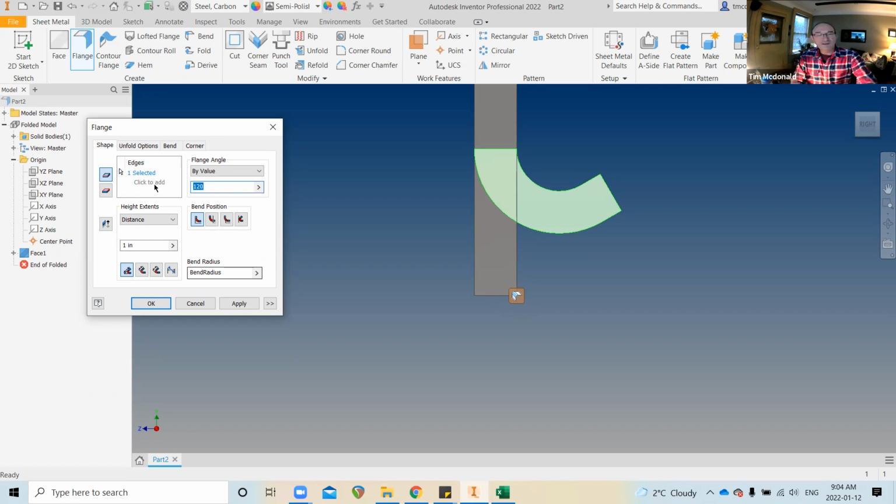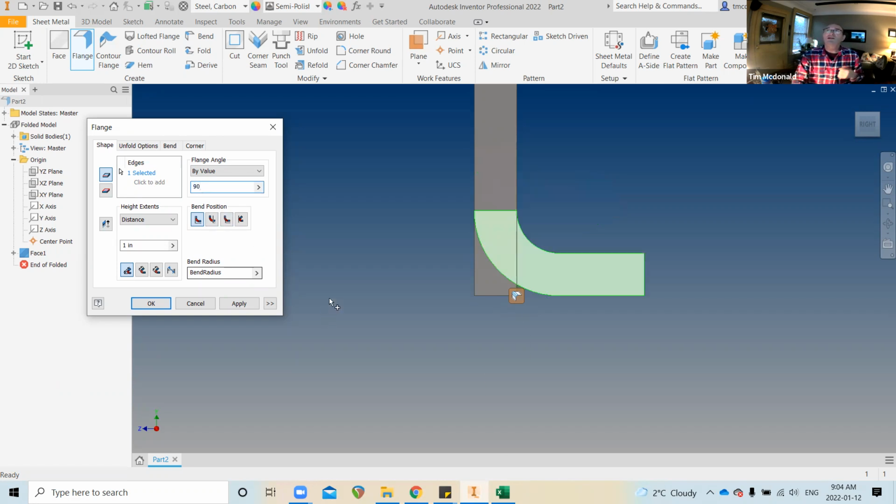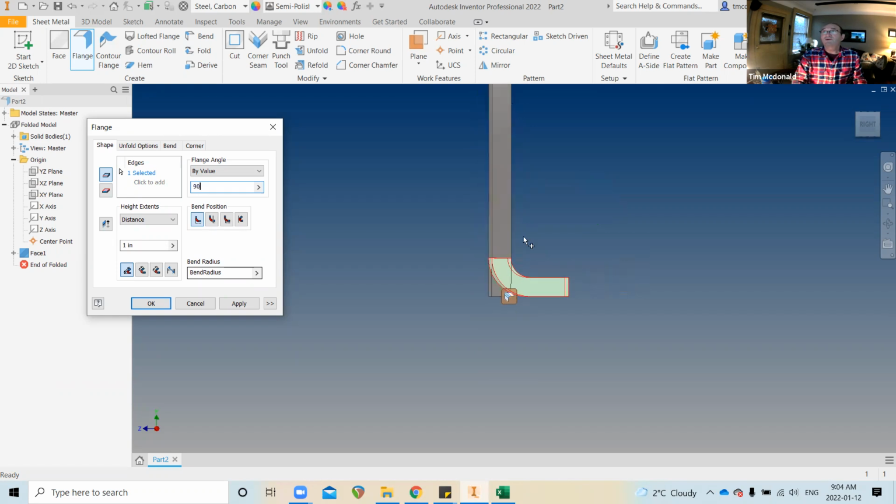So you can play with those options. Those are kind of cool when you need to fit something together. I am going to maintain my 5-inch height in this case. So for me to maintain my 5-inch height, I need that flange within the reference plane. So that is this first option that we have.